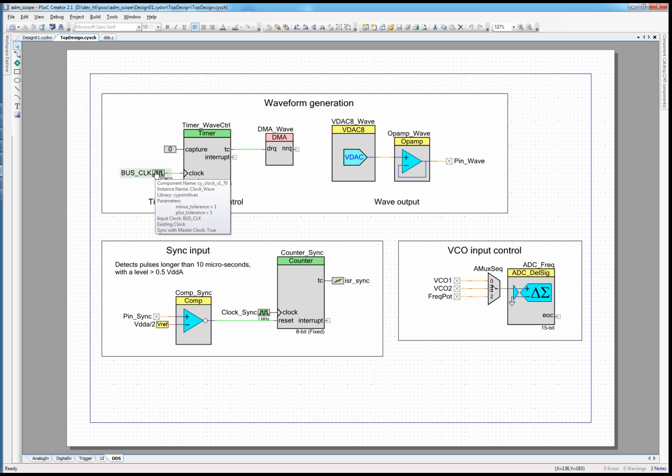with a bus clock of 38 megahertz and 32 steps in our waveform table. We get, even with a divider of 1, meaning we reach this through, a frequency of a little bit above 1 megahertz. If we increase this divider to 2, we halve this frequency, so there is no way to create, for example, 900 kilohertz, because you just cannot do this with that. For that, I have another solution, which unfortunately is in another project.